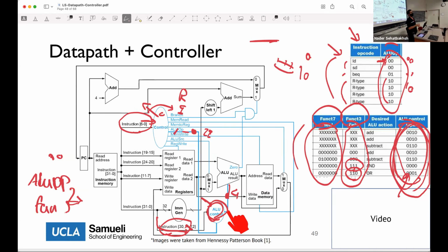Yeah. So again, the why part is that we want to have the exact same processing time for all the instructions. One trick we could have easily done was to have separate opcodes for all the R-type instructions, and that would have been easy enough, right? There were two downsides to that. One was that the decoder, the switch case that we had, would have been much more complicated because now we have more states. We have different steps for add versus subtract versus and versus or.